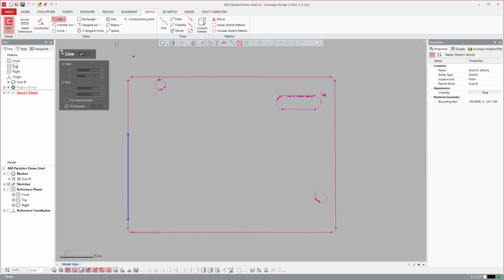We also go through, and depending on the geometry that you're going to create, in this instance a line, we will also try to highlight what we think are lines in this profile here. So if I just roll over that and click it, you'll see that it'll best fit a line to that area as well, without having to best fit by windowing in like we did here. And this works for all of these different entities here.